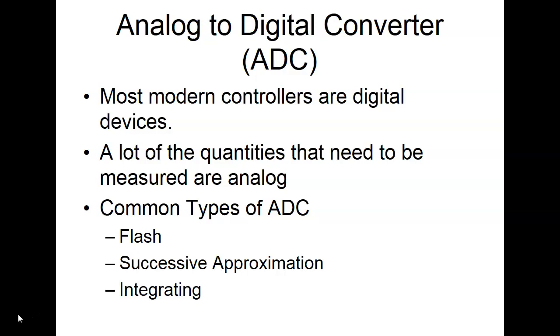But the input to the, I think it's got 5 analog inputs. It's got 5 analog outputs on it. And I think some of the analog inputs are current loops. I have to go back and look. But analog to digital converters, what we're going to do is take an analog value and convert it over to a binary equivalent.